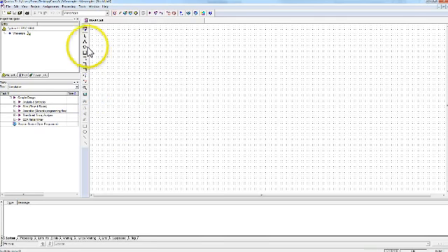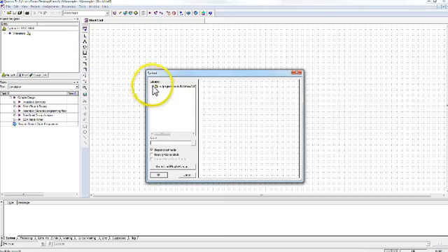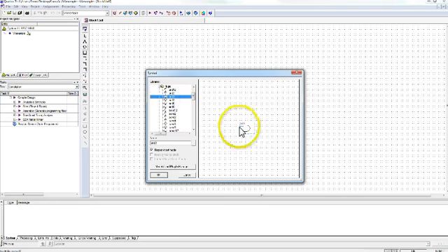All of the gates that you've learned about, AND, OR, XOR, NAND, NOR, they're all present in the symbol tool here. And you can expand this folder, and then expand primitives, and then logic. And a lot of these gates are here, and the naming convention is not too difficult to understand, but if you get confused, just select one and look at the symbol and see if it's what you want.